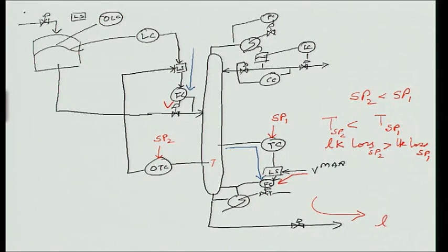There is a flow controller on the feed to the column, and I am setting the feed set point, and I am comparing it with the override level controller set point. The lower of the two signals sets the feed to the reactor or the tank. Okay.